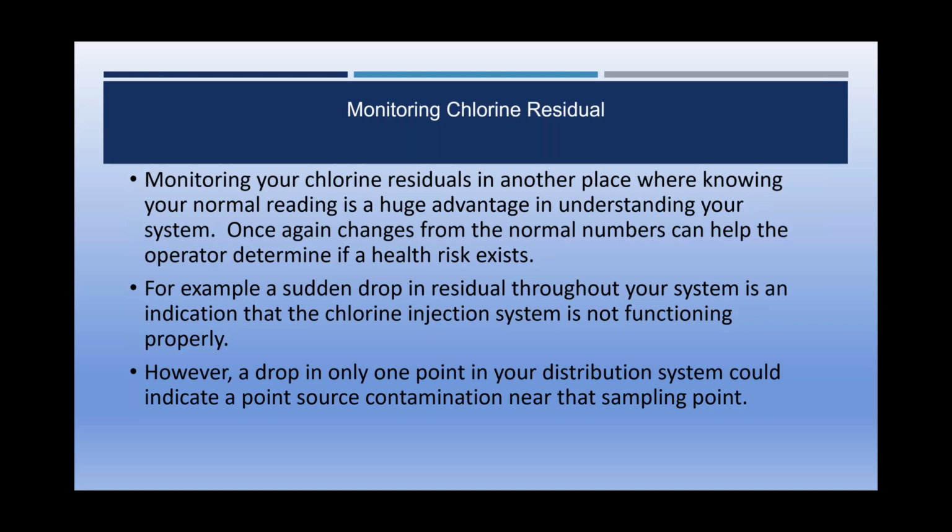So eventually what we ended up doing is we dug up that pipe, pulled it open, flushed it out, and some kind of small animal came out of the system itself. So somehow during the installation, something had crawled into one of the pipes. It wasn't checked, the pipe was sealed up, and we had this poor drowned animal in there contaminating the water. And that's actually not that uncommon. If pipes are left on the ground, creatures will sneak in there.